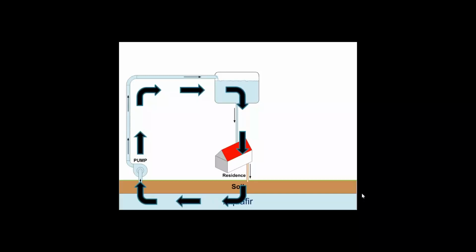So if you grab one side of the 115 volt AC line in one of your outlets, and your feet are standing on a wet spot on the ground, you might get electrocuted because electricity will flow through the ground. Remember, the ground's made up of many elements, some of which are conductors. Now, not all ground is a good conductor. Sand, dry sand especially, is very poor. But anyway, you see the idea of a complete circuit.